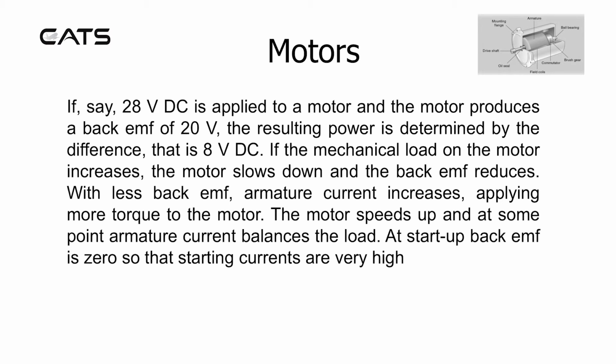This would be, let's say, your electric lawnmower going through long grass, or a drill hitting tough concrete. Back EMF decreases, so more current can flow, burning out your motor.